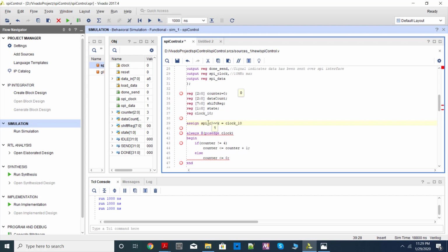So again, you can do it in a different way. Effectively, this is a multiplexer. So I can write like, if clock enable equal to 1, this one. If there is no clock enable, SPI clock remains 1. Now I am using it with assign statement, so we need to remove it. Now from where we will get this clock enable, that also we need to generate, okay, from the state machine.